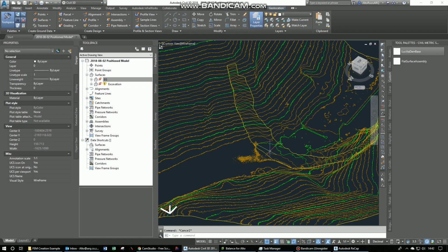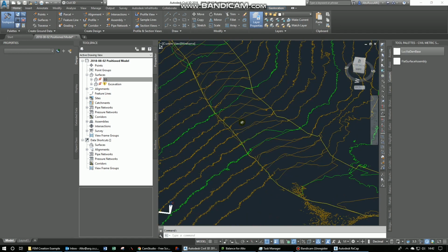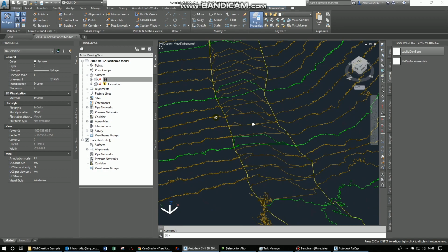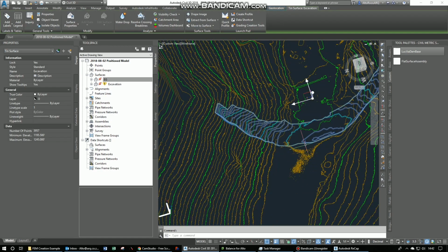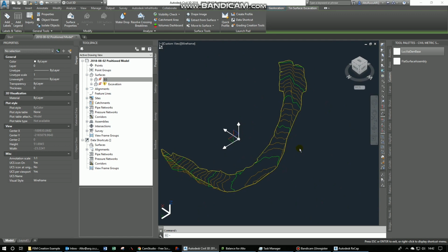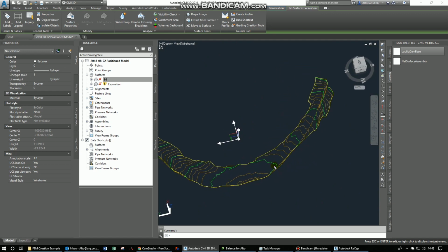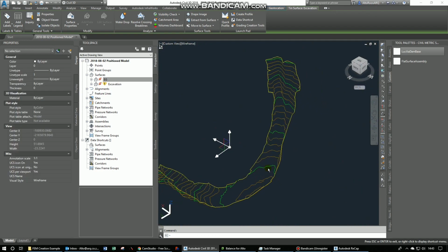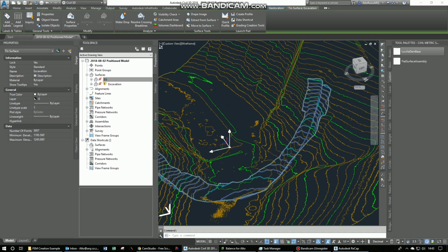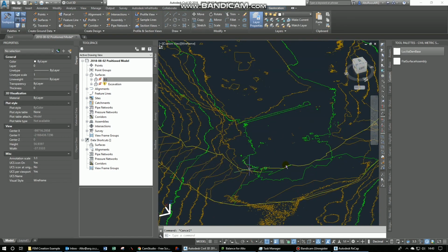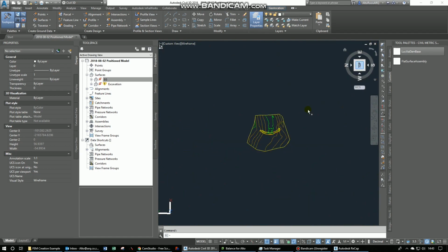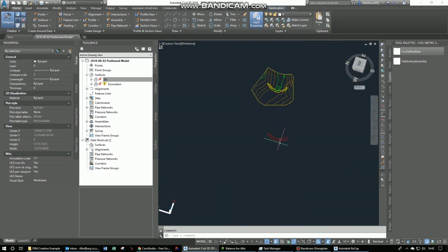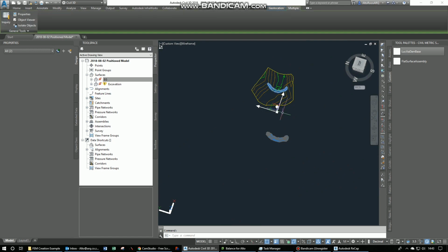We've got another surface in here, which is the excavation plan that was obtained from the design or as-built drawings. It was basically modified off of literally PDFs, where I traced the points, traced the contours, and then added an elevation to those lines, and then we created this excavation plan. We also added a boundary line to that, and the boundary line is at the bottom at this stage. Anyway, the red line you can see is the boundary line for the excavation plan surface.